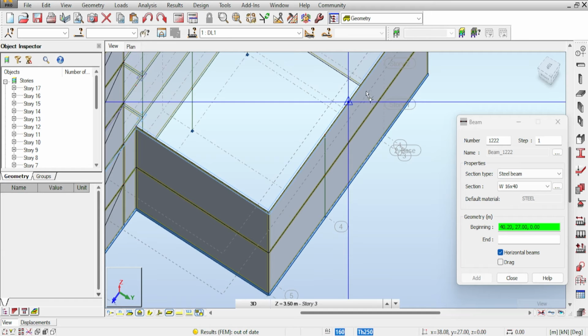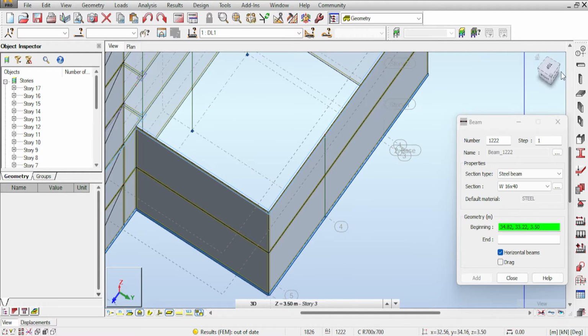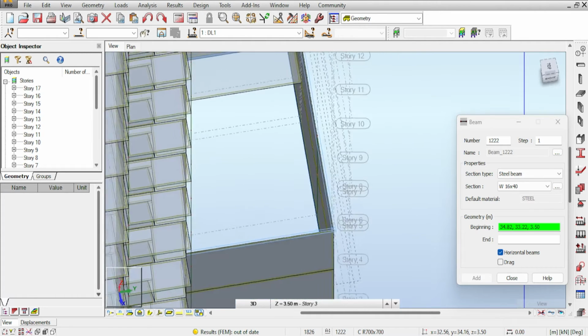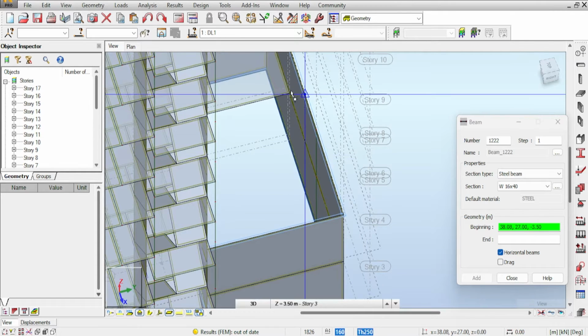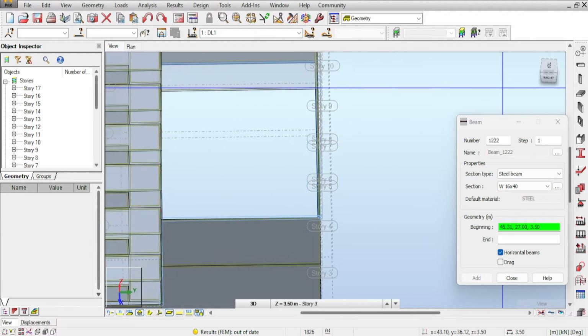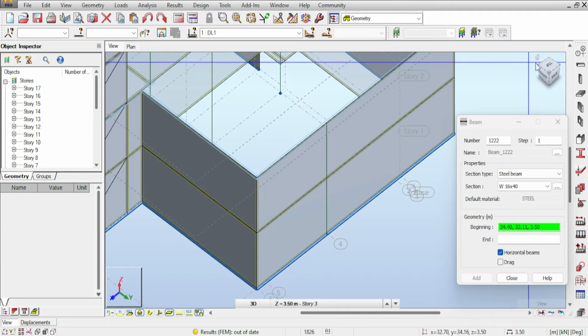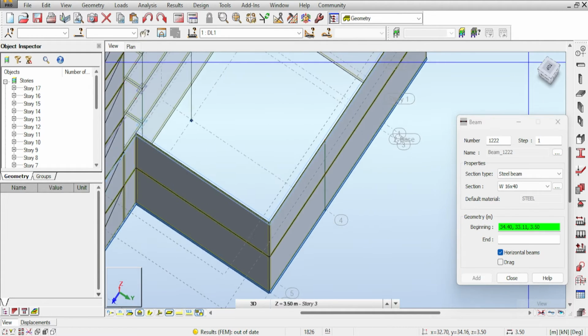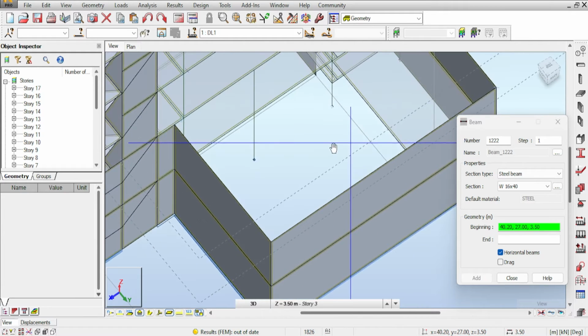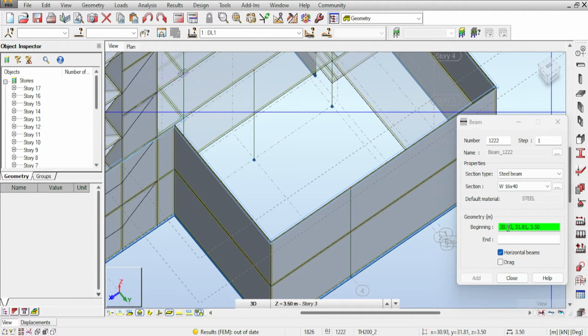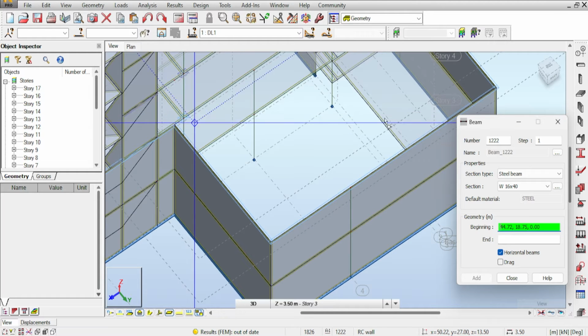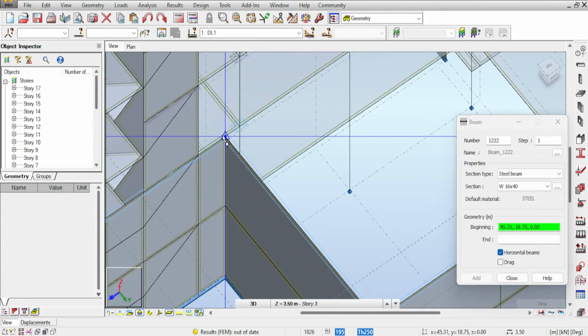Others could say, no, I want the inclined beam to be integral with the wall. And some people even think that there is no need for columns and no need for an inclined beam. I could just cast the incline, like the slope of the car, with parts of the wall. Now this might be a little bit hard because you would need to know exactly where to stop the wall, but that's also another way. There is no singular correct way. I'm open to all possible methods of construction, and it depends really on the regional settings and how you do things. So as long as it's stable, you cannot say it's wrong.